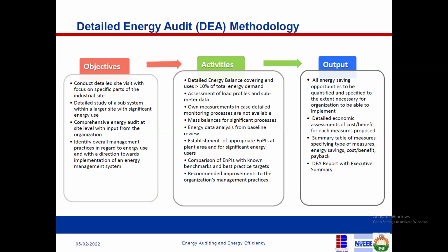Do a load assessment. We'll do measurements. We'll do detailed monitoring. Okay. We'll do mass balance. Okay. We'll now establish our baseline. Baselines are very important. Let's say in the case of a hotel, what is our average occupancy rate? When we're at 50% occupancy, what do we consume? So I know that when we achieve 70% room occupancy, of course, expectedly, the energy will go up. But not when I've established my baseline at 50% occupancy, and then suddenly we're having 30% occupancy, and the energy is still going up.